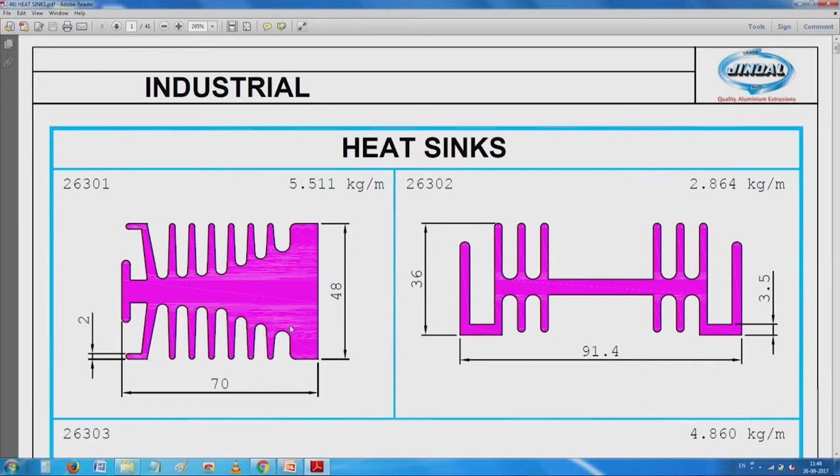So, does the mass help or not? Yes, it does help here. In this case, the best way this heat spreader works is if the fins, all the surfaces are maintained at the highest possible temperature, which depends a lot on how well the heat is conducted to this and how well the heat is taken away from this.